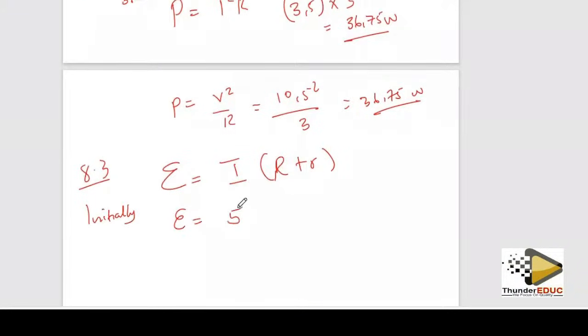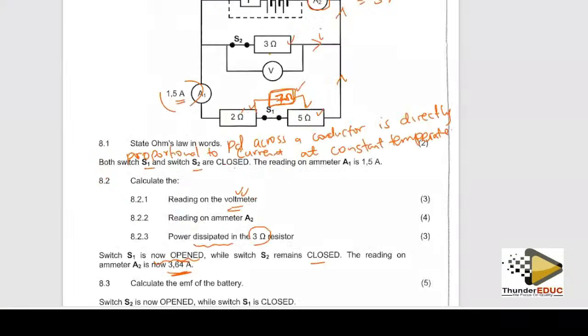So that's going to be 5 into the effective resistance for the total circuit. Remember, this is a 3, that is a 7 combined. So the product is 3 times 7 over 3 plus 7, which is 21 over 10. 21 divided by 10 is going to be 2.1.